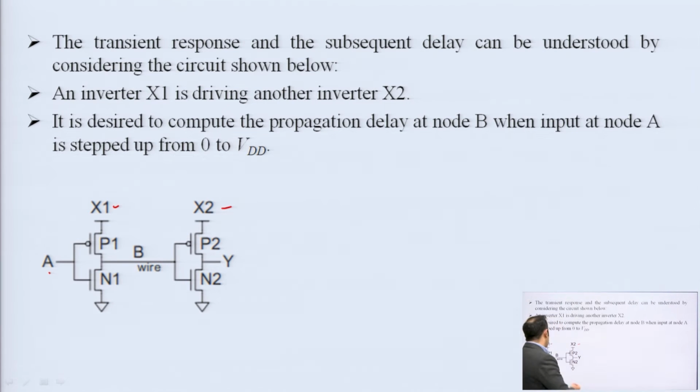You can see one PMOS connected in series with an NMOS. Your PMOS is your pull up transistor, it pulls the output up to power supply, or VDD. Then you have an NMOS transistor which is your pull down transistor which pulls the output towards ground potential.